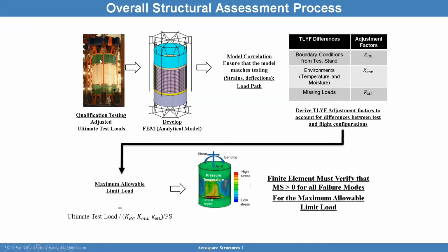Because, for example, if I were to apply actuator loads and then the strains in the structure somehow are lower than in the finite element configuration, you may start thinking, well, maybe perhaps I'm not applying the loads correctly into the structure. So you want to make sure, and there are many cases where one thinks that the actuator loads are putting loads into a structure, but it's actually not. And that's where this correlation becomes important.